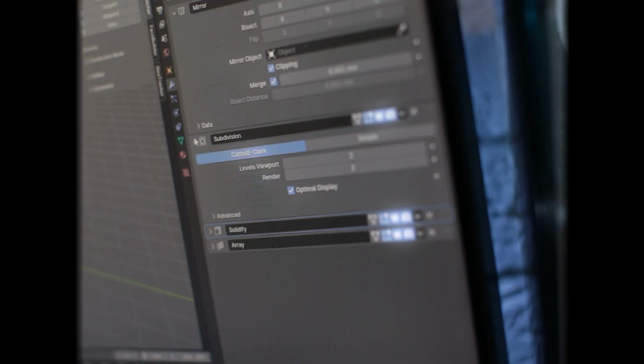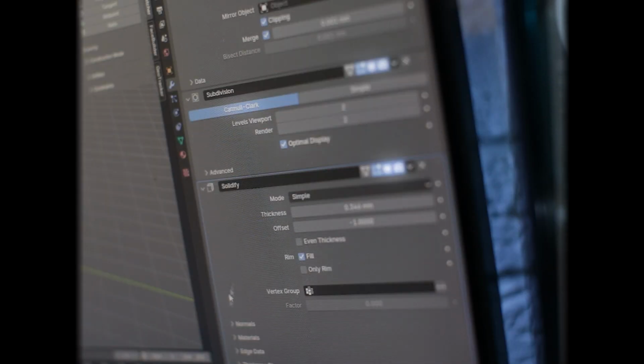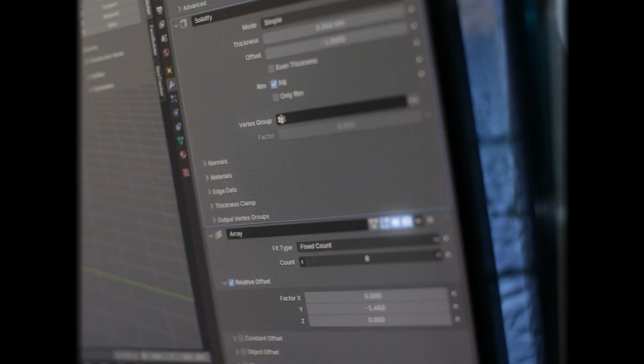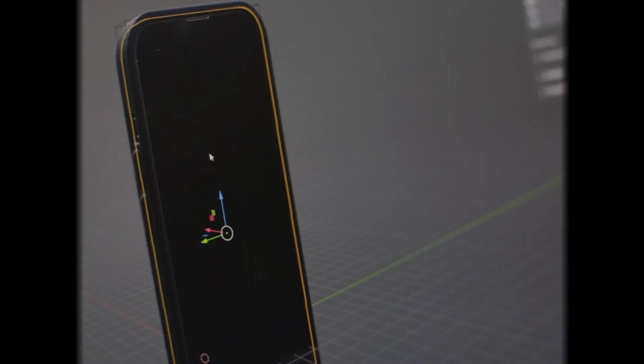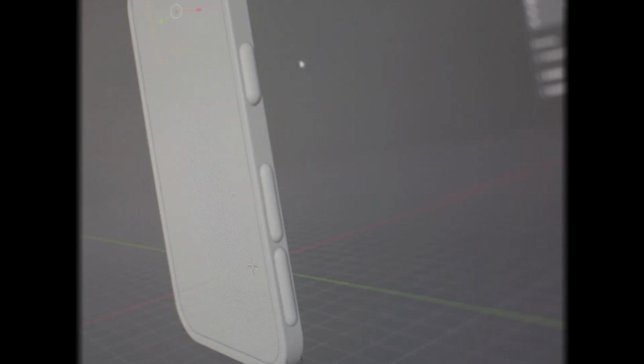We cut off half of it and use a couple of modifiers to make it easier to work with multiple bubbles at once. I copy them 5 times onto the back cover and get the first shape. To fill the space next to the camera and avoid creating visual noise, I simply rotated our speed bumps 90 degrees. Next, we look at where the buttons of the iPhone are projected and create the same bubbles on the surface of the bubble case, but they will not be full so that they can press our buttons.